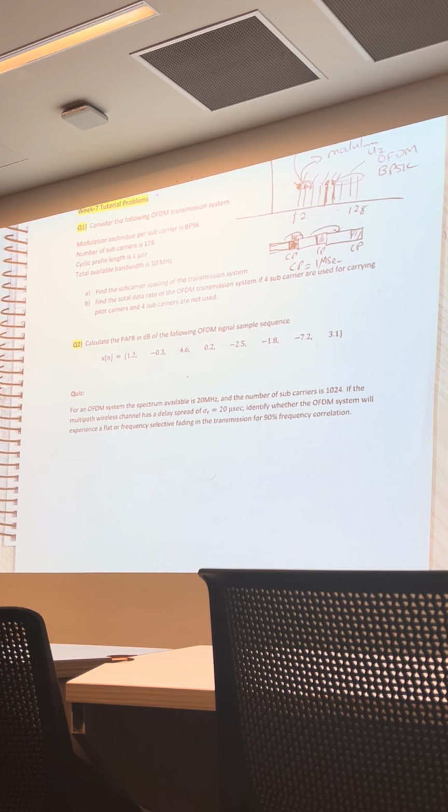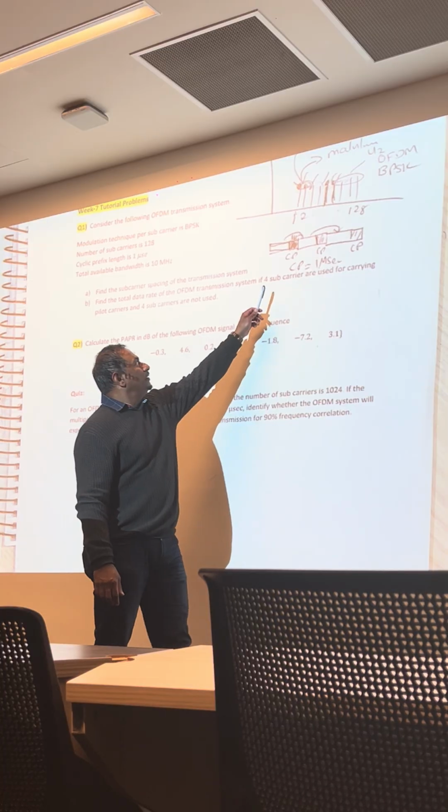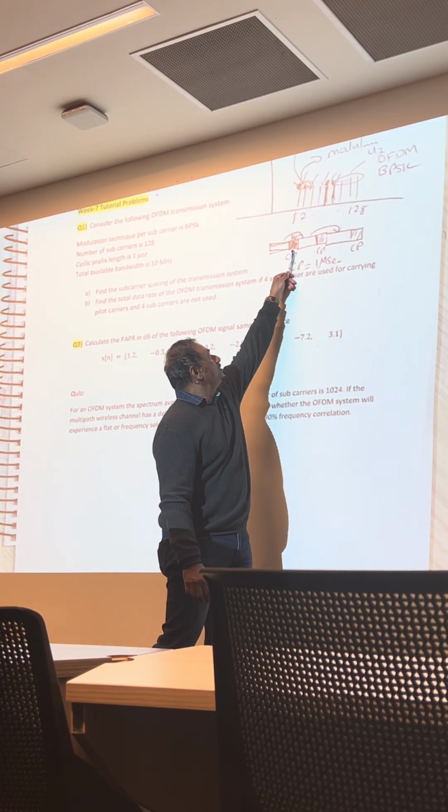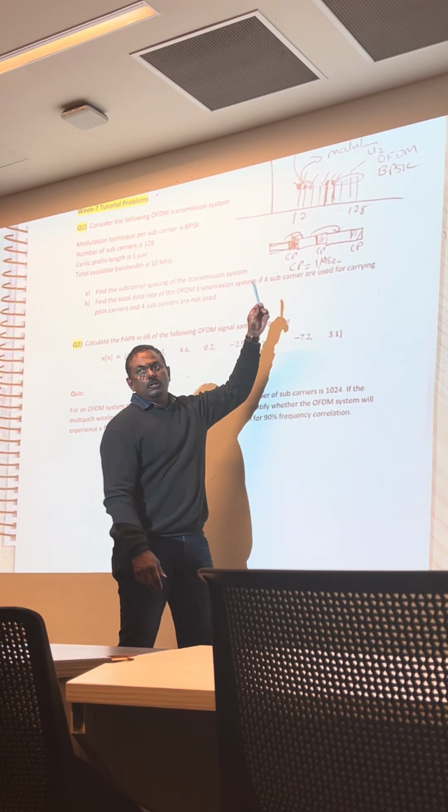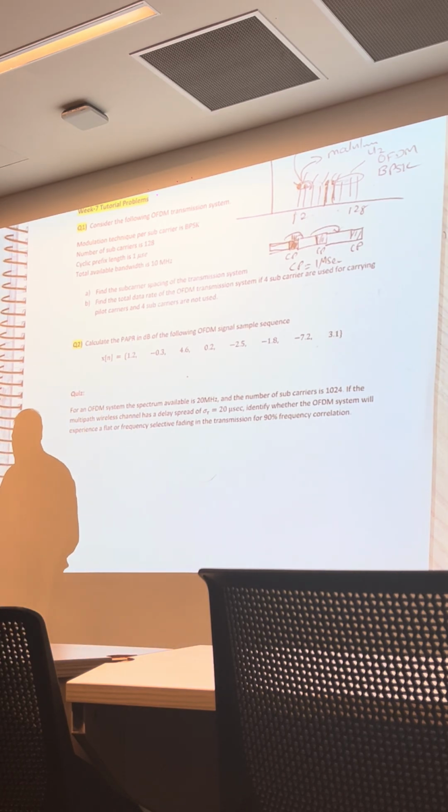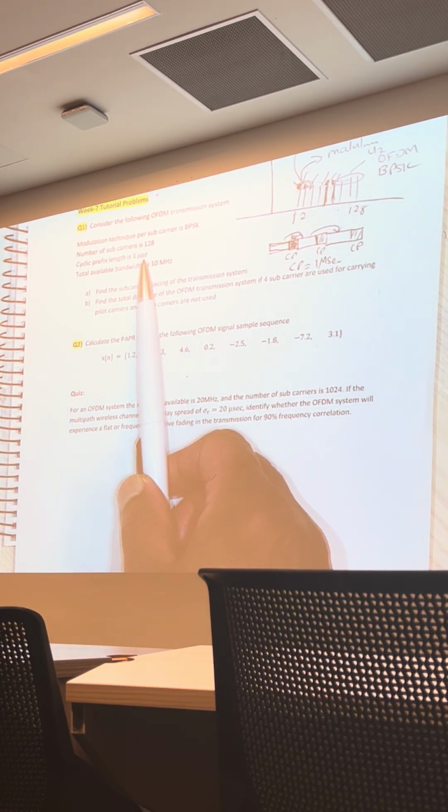There are options, like 2 or 3 or 4 options according to the standards where you can alter, but the receiver should be notified of that. Otherwise, you wouldn't know where the symbol lies. If you accidentally discard a different amount of data instead of the cyclic prefix data, then you're losing data or information. So the cyclic prefix is 1 microsecond.